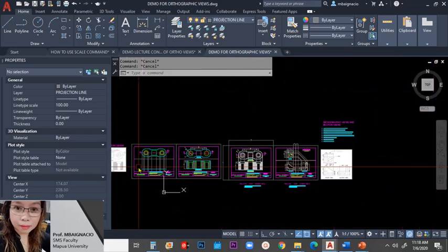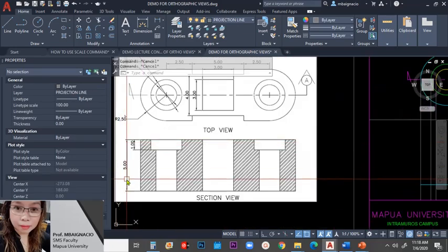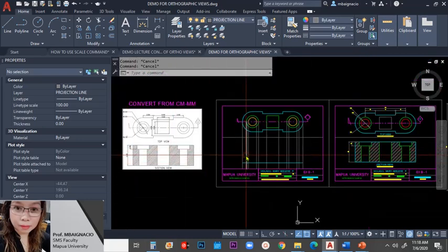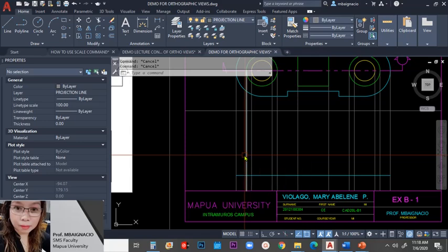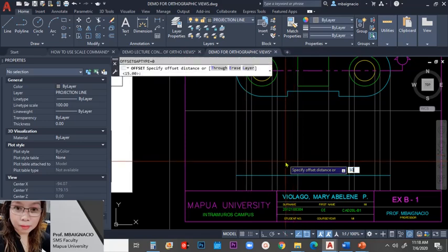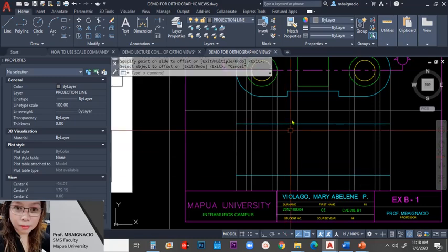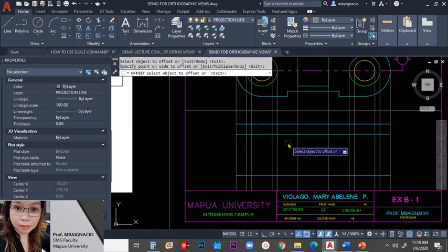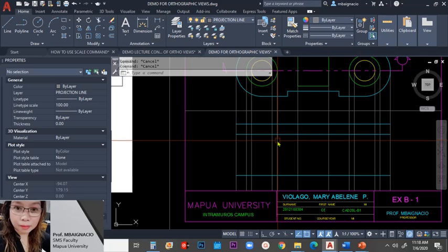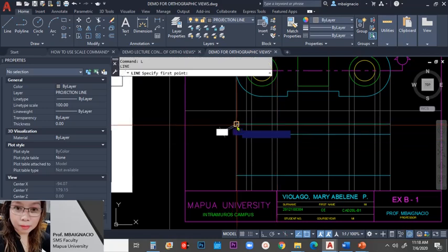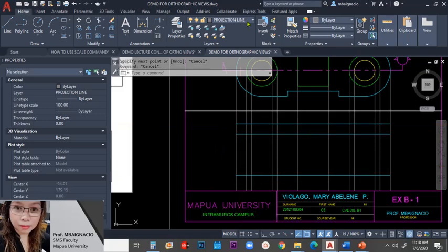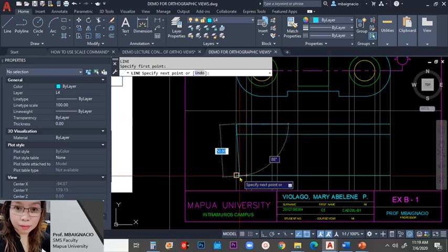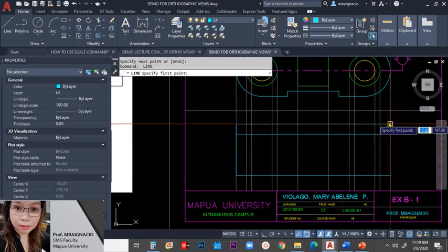And then you have a reference height. The reference height given here is 5 with an offset from the top going here at 1. So convert it into centimeters, that's 50 and 10. So offset 50, and then another offset 10 going down. Then you can trace a line, create a line passing here. You can turn on your L4 so that you can layer it accordingly. So this one and this one.